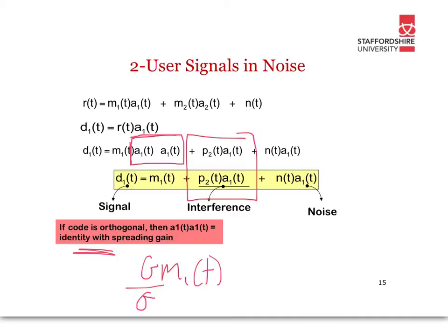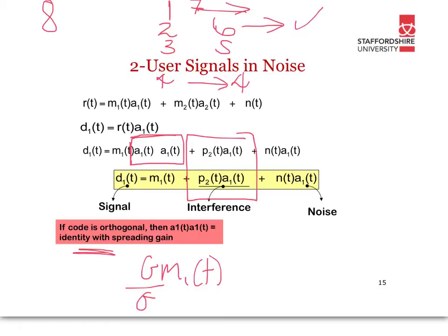Previously we had a gain of 8. What this means is if one bit was received in error out of those 8, then we would still get the correct result. If 2 bits were received in error, then 6 would still be correct, so we'd still get the correct result. If 3 bits were received in error, then 5 bits would still be correct, and we'd still get the correct result. However, if 4 errors were made, then we'd have 4 bits in error and 4 bits correct, so we would possibly not get the correct result.